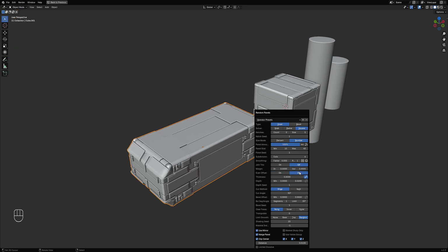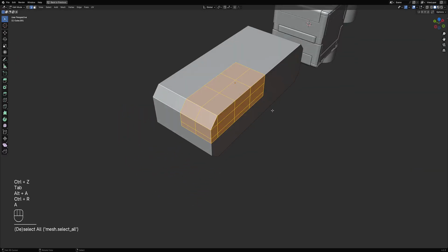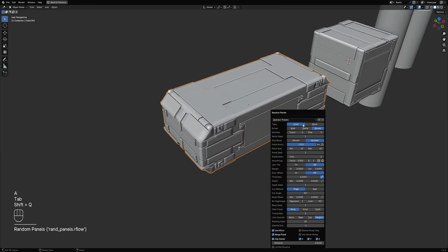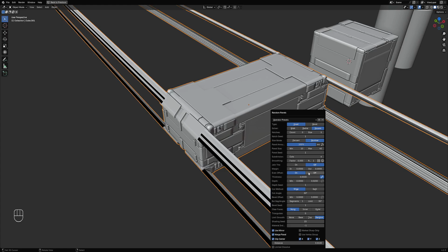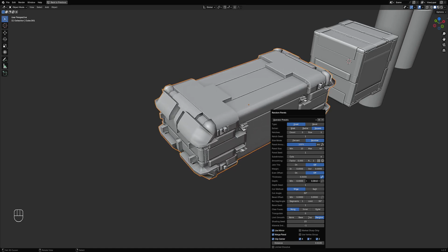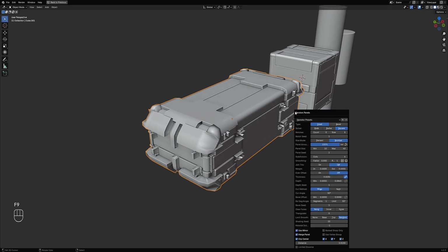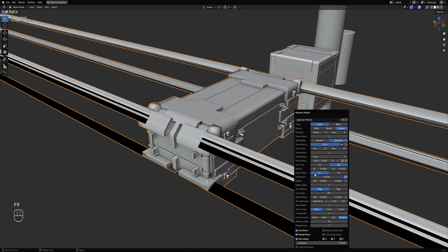Oh, off. Okay, it's supposed to be off, not on, to get rid of the geometric spiking. Well, let me just show you how you can get rid of it. Okay, so for example, even offset is on. You can try turning it off, but the inset depth or extrusion will no longer be even and is going to be curved at the sides versus even offset being on.